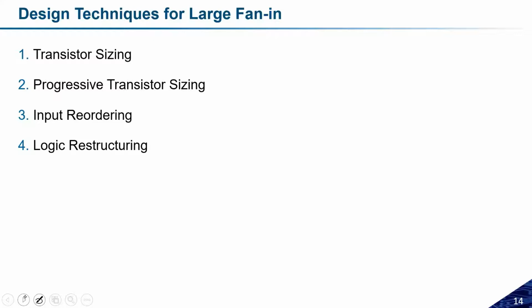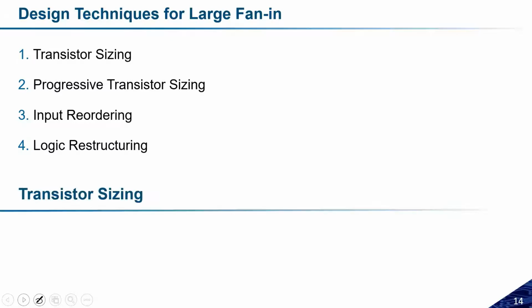In that case, what I can do is simply increase the size. Okay, so let us discuss these things. Let me write a few things here. The propagation delay will be reduced if I increase the size of the transistor. But if I increase the width of transistors, the propagation delay will be reduced. Let me write in the opposite way.